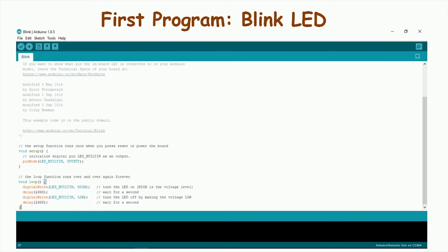That was just a quick overview of LEDs. If you have to blink an LED, it would take only a few lines of code. If you observe this code closely, you will realize that some part of the code is black or dim and some part is colorful. This black or dim part is the comments of the program. Comments are the part of the program that is written specifically for the programmer or reader to explain the functionality of the program. Comments do not take space in the microcontroller's flash memory. They are also ignored by the compiler.